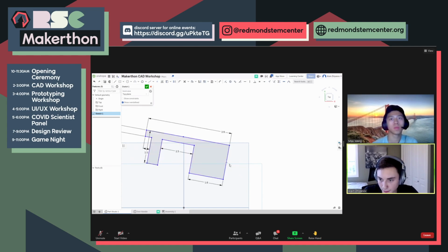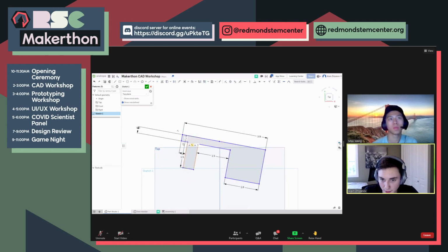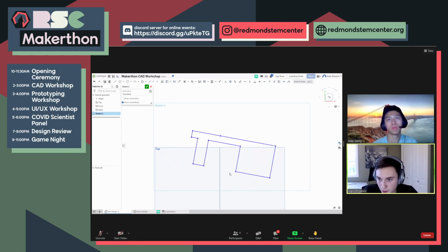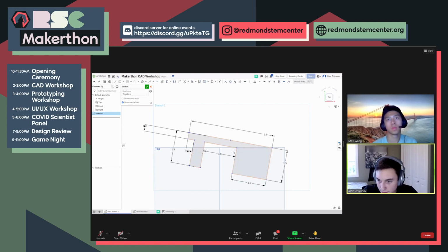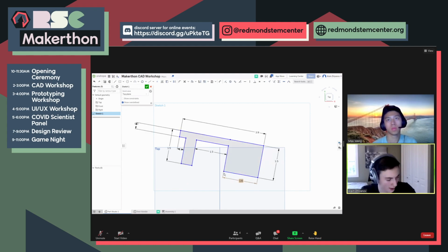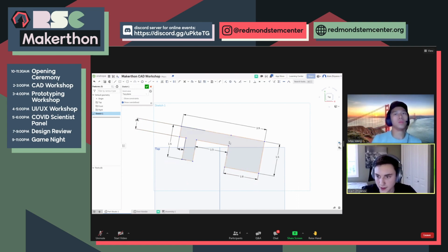Oh, the length of this. Let's say I want it to be about equal to that. So I'm going to go ahead and set that to 1.5. And we're getting pretty close to our goal shape here. See how points are moving around just because it's two lines. Okay, so that looks pretty good, actually. I think now all we're missing, this looks a little bit small, actually. Yeah, so it's a very trial and error process, just getting these right constraints.